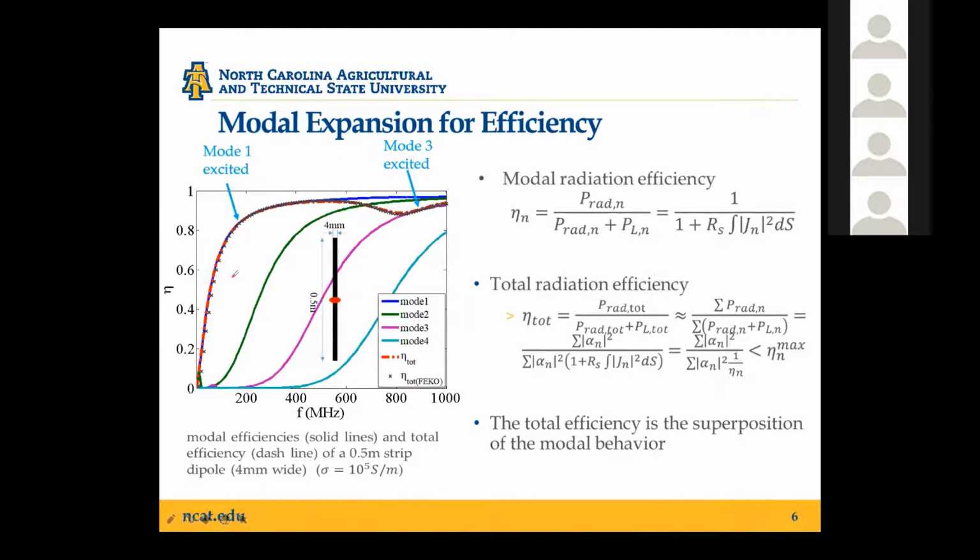So all these examples essentially demonstrate that, with characteristic modes, you can pretty much access any parameter for an antenna. Of course, here I didn't show the radiation pattern. You can do the same for the radiation pattern as well. So all the input parameters, secondary parameters like Q factor and efficiency, and far-field patterns, you can expand them once you know the modal response.